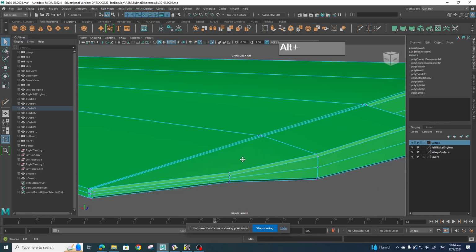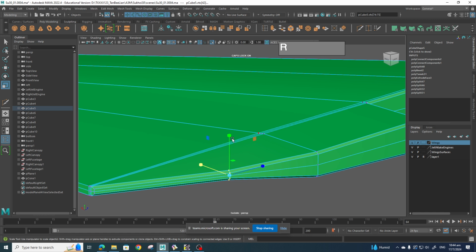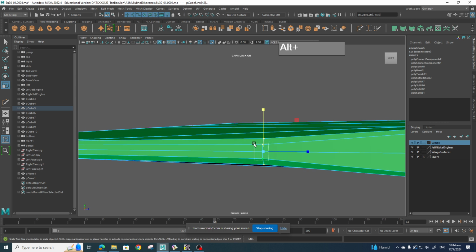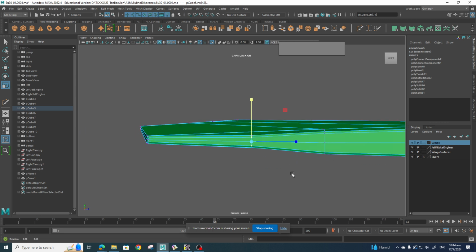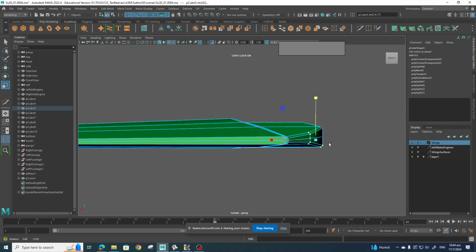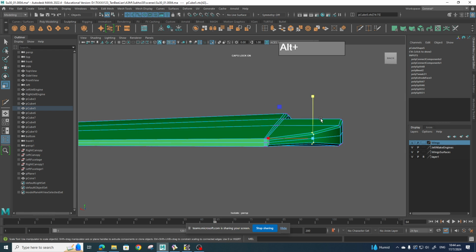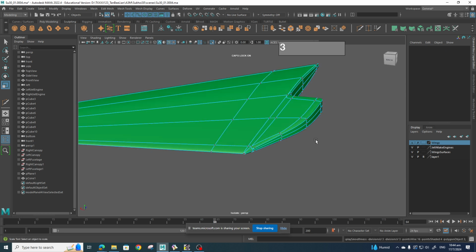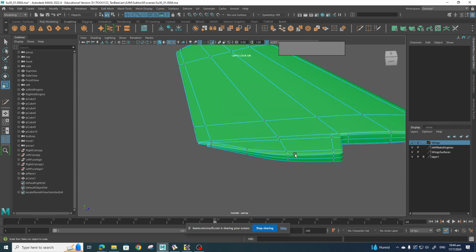And these vertices over here, I think they can be scaled up slightly so that we can form a much nicer transition for the taper. These two here, I'm going to just pull them out slightly a little bit more. We're looking at the angle here. Maybe, oops, not these two, only this group here. And just use a scale to scale it up until we see a nice transition. Okay, so if I press number 3, right now I have a much nicer section here.